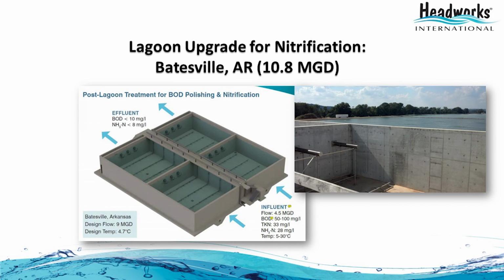The main reason was that in winter the temperature is very low, can be 4.5 degrees at the lagoon, and over the years the population grew and the industries around the plant grew, so they had to expand this plant. They looked at multiple options. Then they chose MBBR primarily because of the small footprint. So we designed a two-stage, two-train system. The system is designed for 40 MLD, and we designed 20 MLD in each train.